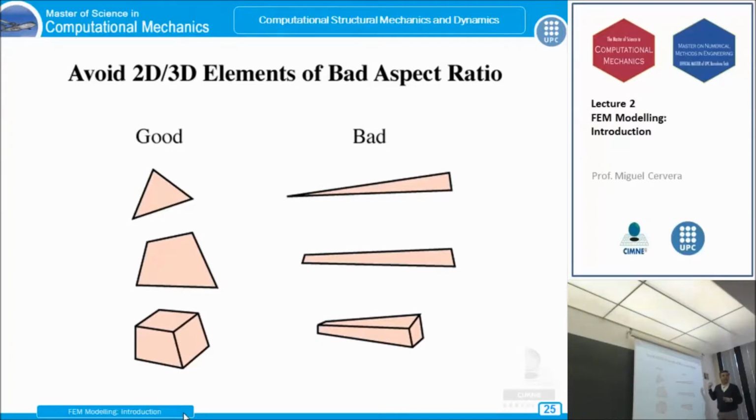So it will easily go unnoticed, but we are going to have what we have shown in previous slides. We are going to have solution error, and it will mostly go undetected. On the other hand, we are not going to do the mesh by hand. So we are going to have maybe a 3D complex model, and then we are going to press the button. And how are we going to know that we have such a nasty element inside a 2 million element mesh? Well, difficult to know, isn't it? So this may happen. If it happens, it's no good news.